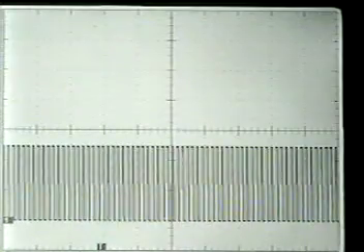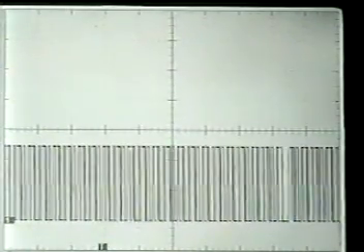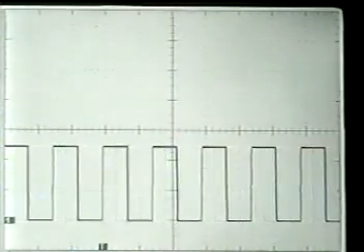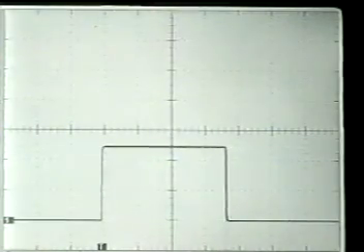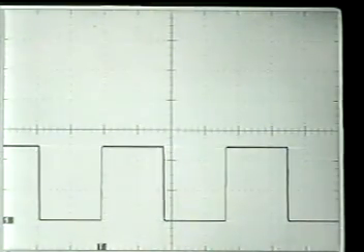The mistake a lot of technicians make is they may show only 1 or 2 toggles on that screen, and you have minimized your chances of seeing a glitch with just, let's say, 2 or 3 toggles on that screen. So in the event that you're looking for glitches, give your scope more time with a whole bunch of toggles, which will increase your chances of seeing that signal dropout.